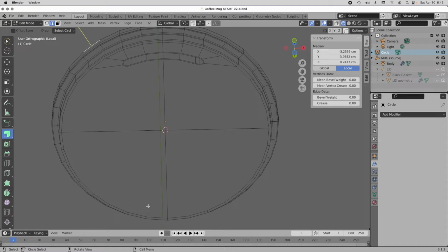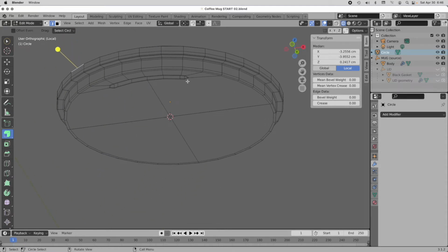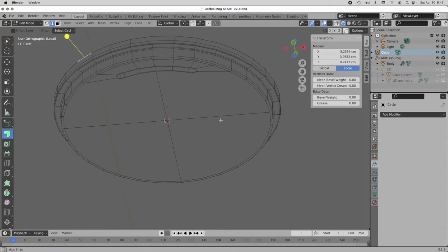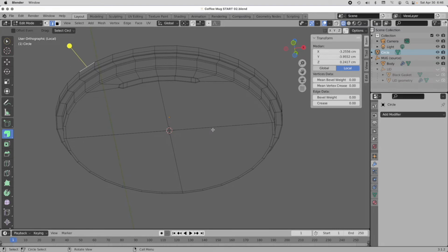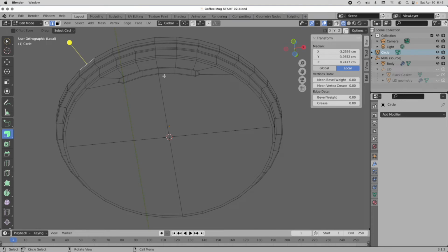When you're working with planar regions, this whole bottom area right here is going to be a planar region. You can play a little bit more fast and loose with how your polygons are set up. But what you typically don't want to remain are n-gons that can tend to back in on themselves like that. You can get irregular subdivision artifacts, and you don't want that.